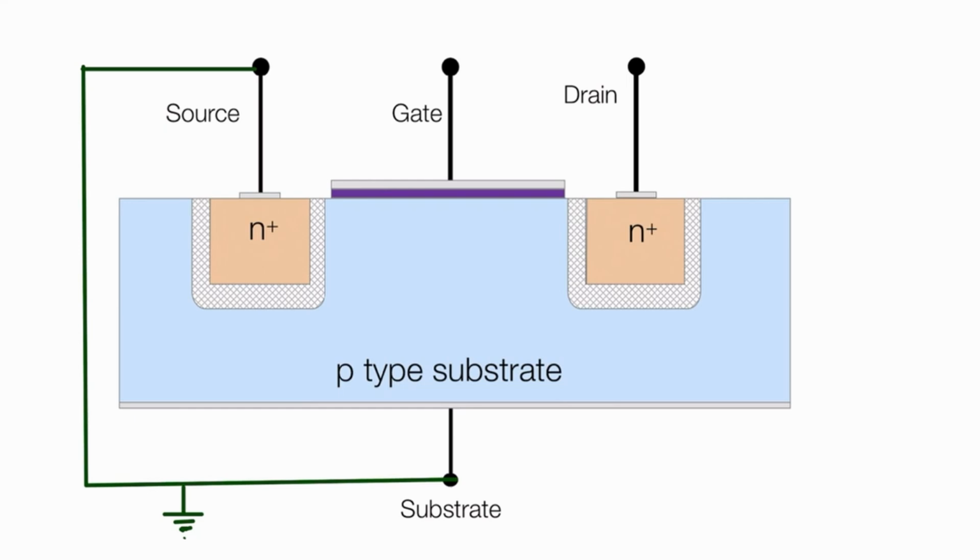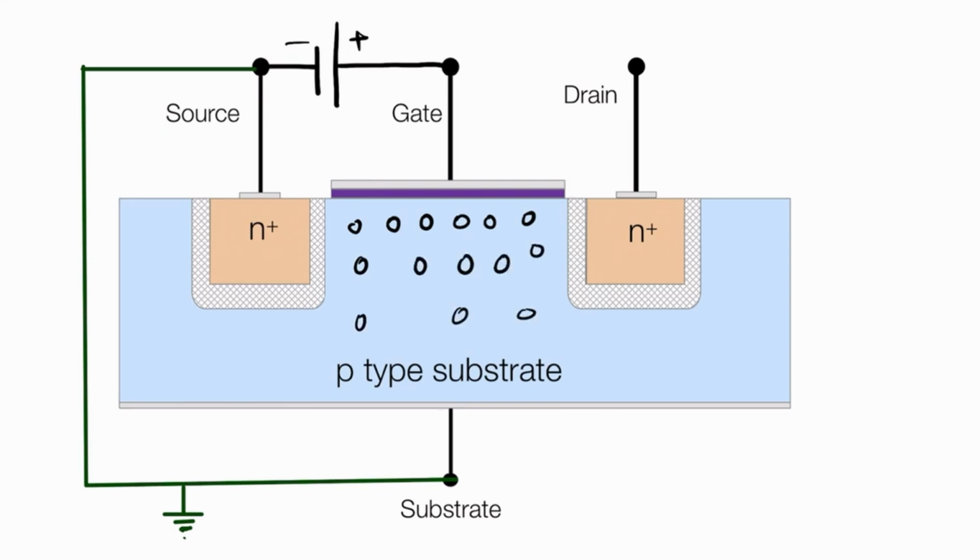So let's connect a voltage source VGS to the gate to source terminal. Okay, this is an n-channel enhancement type MOSFET. So the substrate is the p-type. That means here we will have lots of holes, as it is a p-type substrate, so the majority carriers will be holes. And for the N plus, this is a heavily doped N-type semiconductor, so the majority carriers will be electrons. So the free electrons will be much higher in this area.